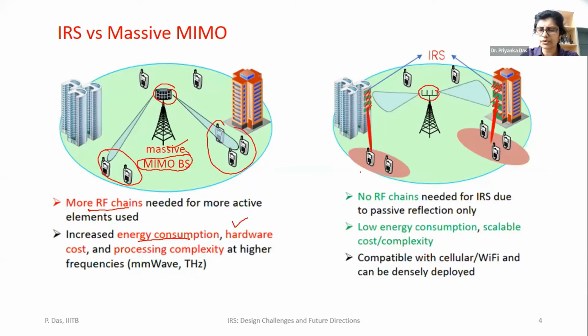Okay, what will IRS do? So for a signal, which is MIMO, here we can do the beamforming, and let's call it active beamforming. The terminology I will be using is active beamforming, which means your base station or the access point will transmit the signal via active beamforming.